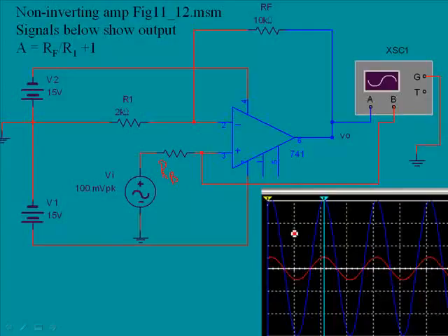It has no impact because we have 100 millivolts in, and that's what you see. There's nothing dropped there, and that's what we would expect. Then on the output, at 200 millivolts per square, we have 3 squares, and that would give us our 600 millivolt output with an input of 100 millivolts.